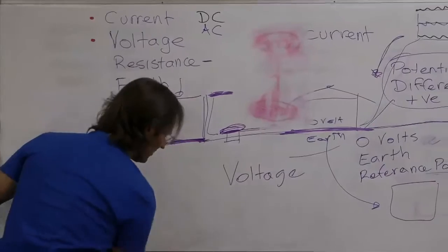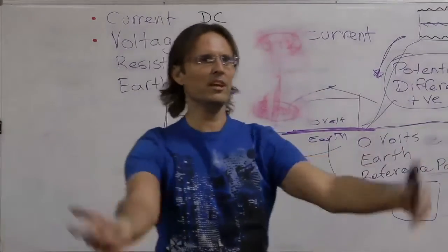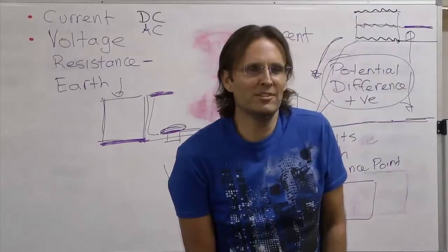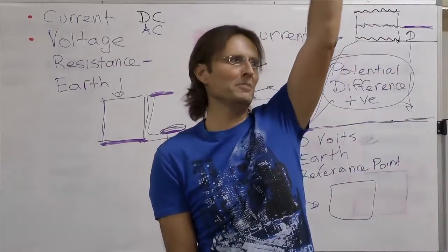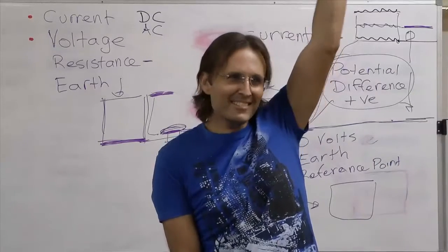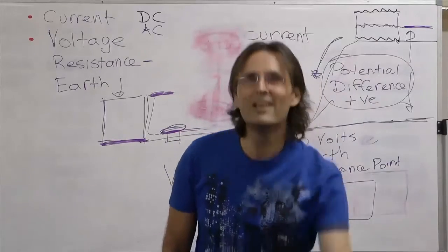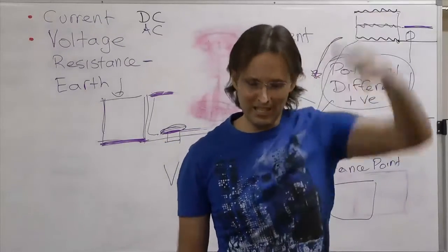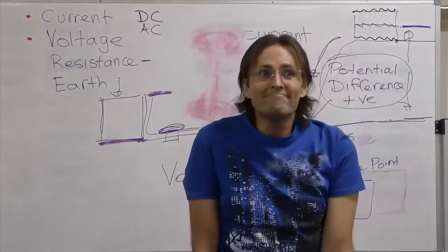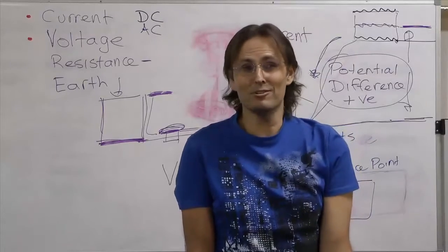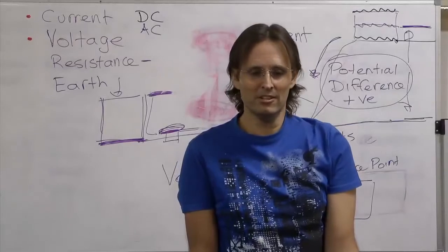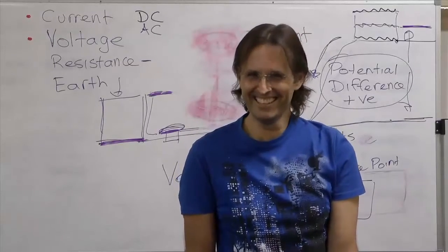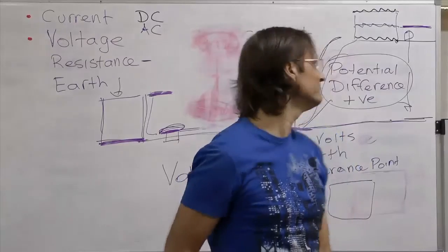You can see that I could say, I'm standing here on 0 volts on the earth, I'm fine. And that's not strictly true. Because you could have a cloud system above you at minus 1,000,000 volts. Does that make sense? And the potential difference between the earth at 0 volts and the minus 1,000,000 volts up there might be tens of millions or 20 million volts or whatever, and if I'm at the highest point in between those two places, I am not very safe at all. So this is why in a lightning storm, if you're on top of the hill, it's a good idea to go down from the top of the hill and maybe lay down on the ground.